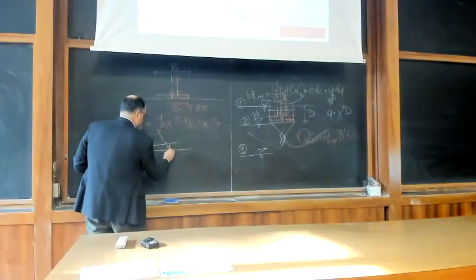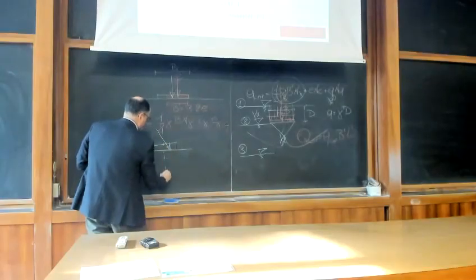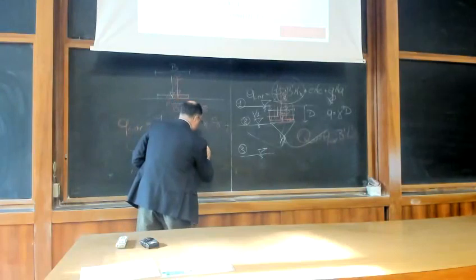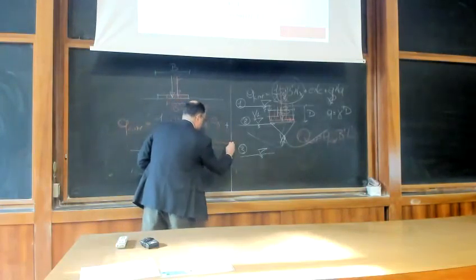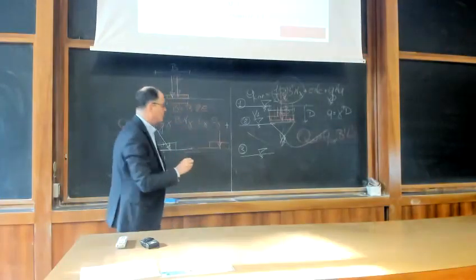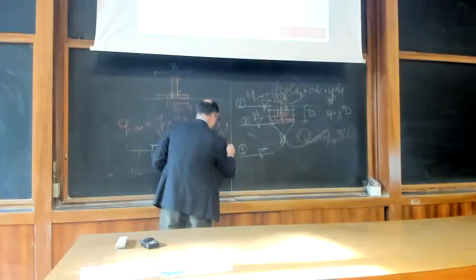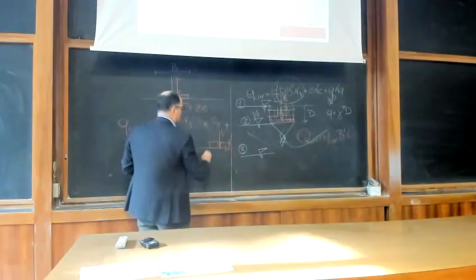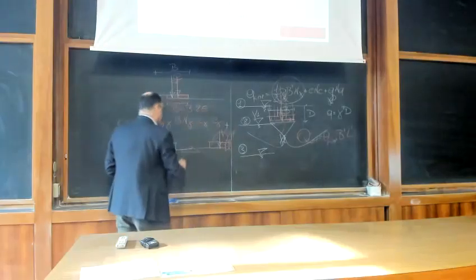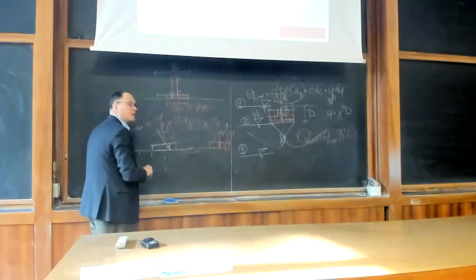So this resultant load, if you have, this is your axis of symmetry, can be considered as a footing where you have a vertical centered component V, a horizontal component H, and an overturning moment M. So the two things are absolutely equivalent, statically equivalent.